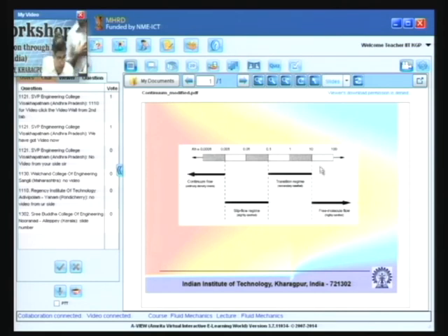And here we see beyond a Knudsen number of 10, this regime is known as the free molecular regime. From a Knudsen number of 0.001 to 0.1, the continuum approach is valid, but not with the no slip condition, but with slip at the boundary surface. That means the fluid velocity relative to the solid surface, the tangential velocity of the fluid, is not 0.